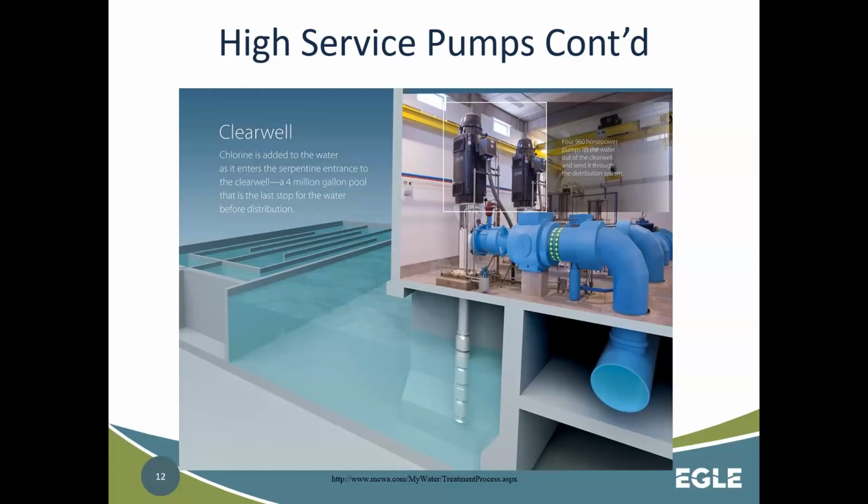You can see the size of the massive vertical pumps here. This is where our big, massive check valves, 20, you go through 24 up to 40-inch pipes, right? Ductile iron typically. This is where some of your SCADA controls, your pressure inputs, your flow measuring devices are coming in from.